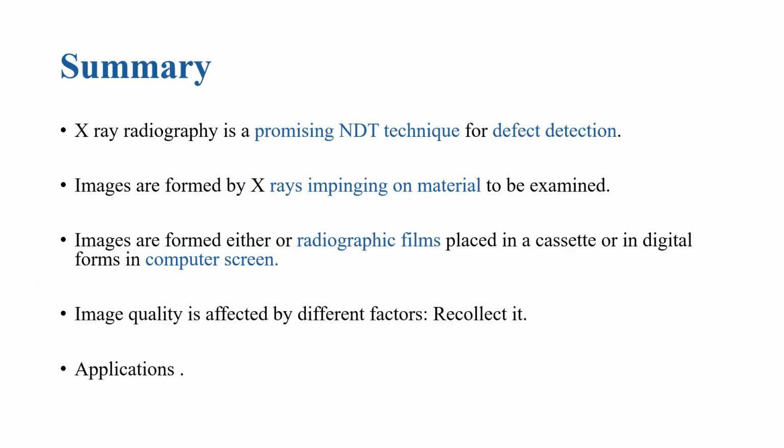As a summary for this lecture, today we have discussed X-ray radiography and found that it is a promising non-destructive testing technique for detecting defects in materials, castings, welding, etc. Images are formed by the X-rays imaging the material to be examined, either on radiography films placed in a cassette or in digital form on computer screens.